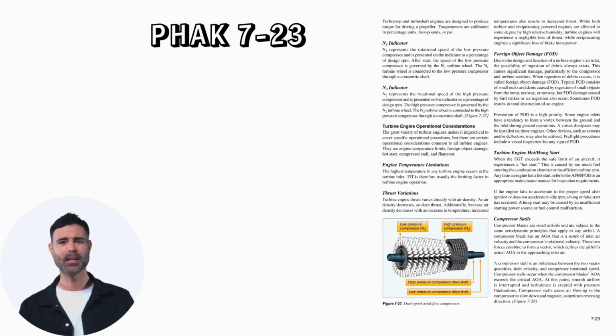Engine temperature limitations. The highest temperature in any turbine engine occurs at the turbine inlet. TIT is therefore usually the limiting factor in turbine engine operation.